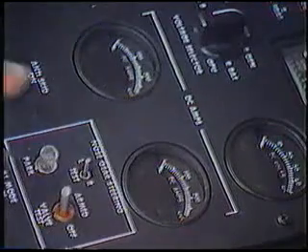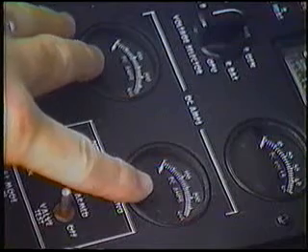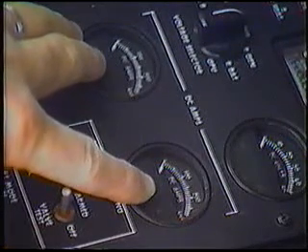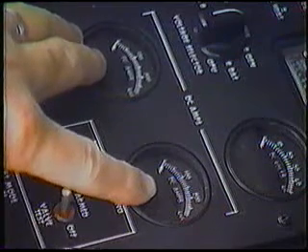The generator ammeter is used to indicate the amount of electrical power or current flow the generator is actually supplying to the aircraft bus system. A generator disconnect light senses the position of the main contactor relay. When the relay is in the relaxed position, the annunciator panel generator fail light will illuminate.